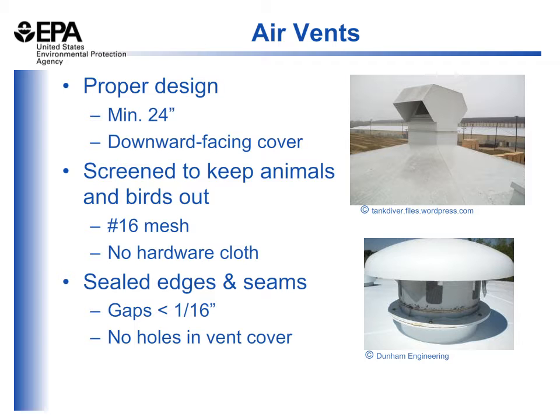And again, make sure the vent opening is screened to keep out animals or insects from the tank. When you select a screen or a mesh size, you want to select a mesh size small enough so that you keep the animals out, but large enough so it won't become a problem or become frozen or blocked during freezing temperature situations.